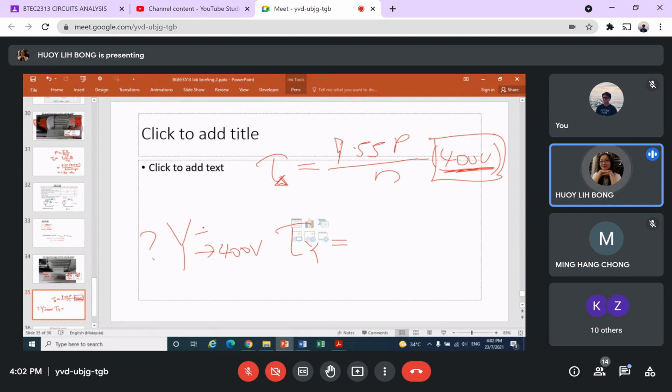By right, it should operate at 692 volt. Then it will be the same torque as the delta. But since it's not operating at its rated value, it's operating at lower, so we can just divide by 3. It's 1/3 of the delta torque if we want to get the star torque.